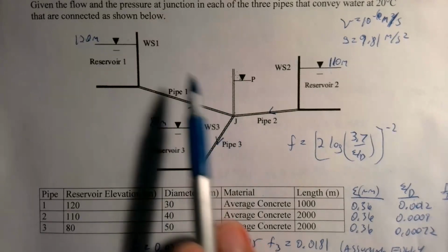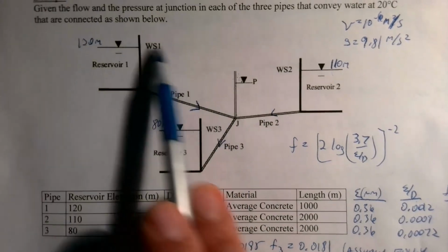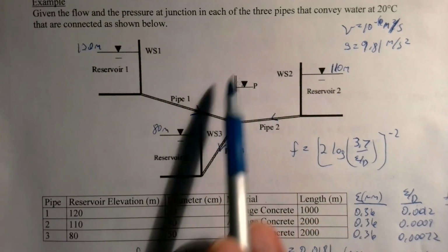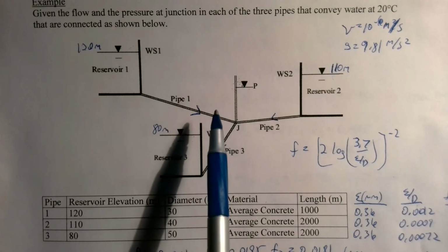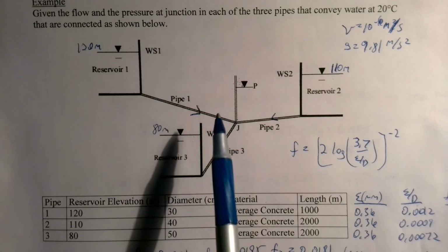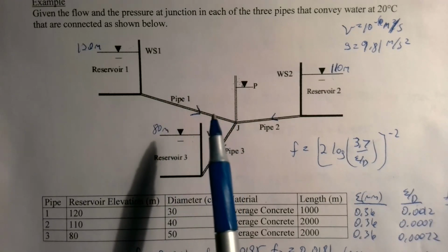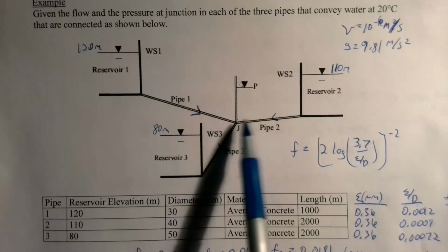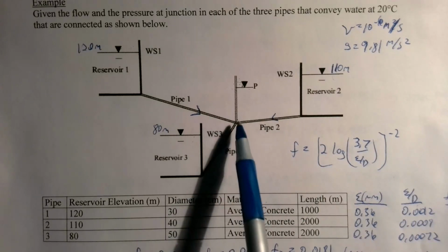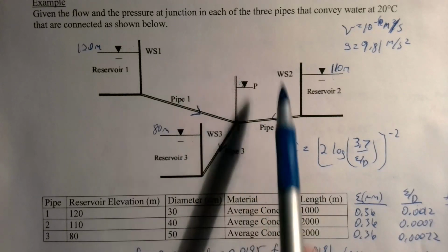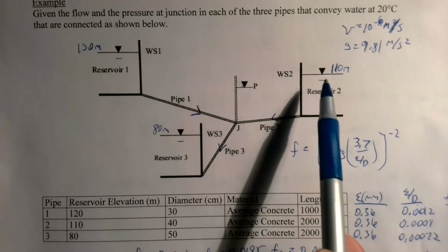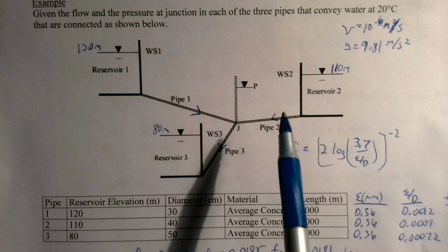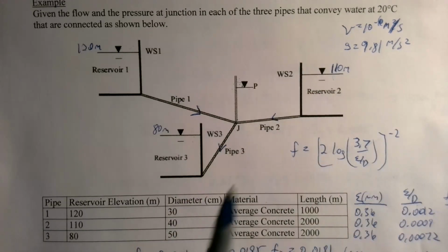And the way that we're going to analyze this junction is by looking at the head difference between those 2 junctions, and making sure that the mass that flows in has to be equal to the mass that flows out, and we also have to make sure that our Darcy-Weisbach equation, or whatever energy equation we use for each of those pipes, is obeyed. And then in a real system, you'd have more than these reservoirs, so you'd have to set this up for every single node that you're looking at. So we'll talk about how you can do that briefly in the next video.